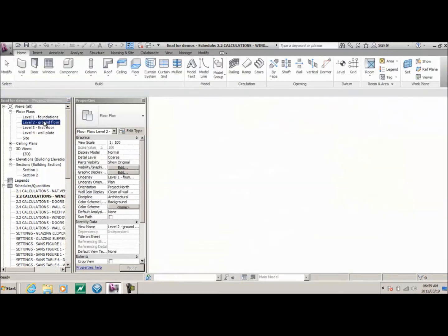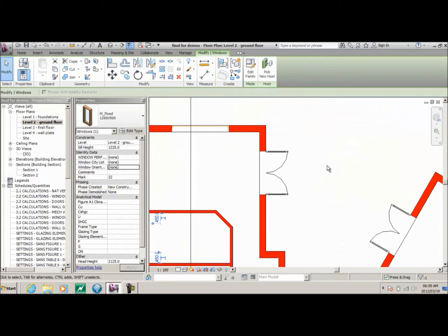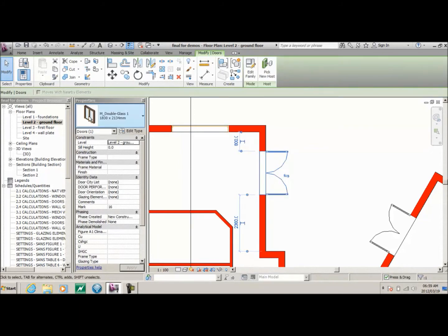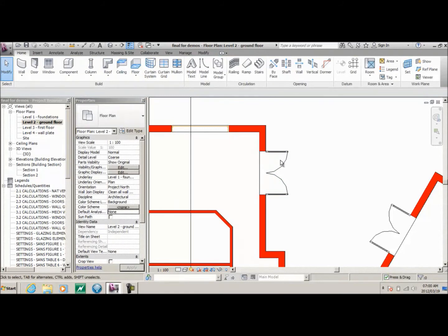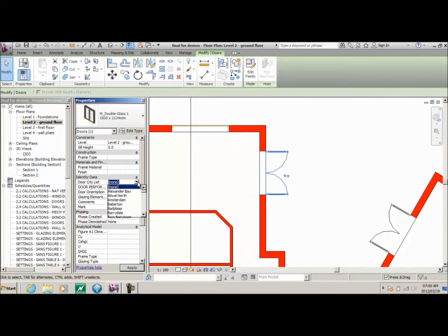Now it's slightly different for the doors simply because we're not actually looking for a material, we're representing elements here. So all you need to do when you would like to specify a door that has glass in it as a glazing element is you need to select it and obviously apply the standard properties here, but I've included one called glazing element status, which you'll just have to set to yes in order to show that the door specifically is a glazing element. You can then go through and assign the rest of the values as well. That one's Joburg, performance, and this one is looking east.